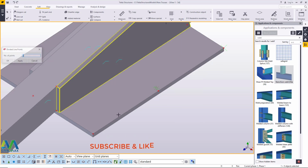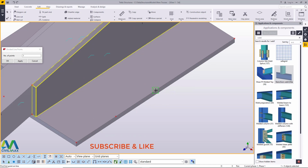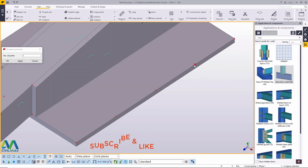I'll come back again to points and pick this point and pick that point. You can see I've located a point between these two points, and come again and pick that point and snap right there. You can see I have a midpoint here. Now these are midpoints I'm going to use to place my holes for the bolts.